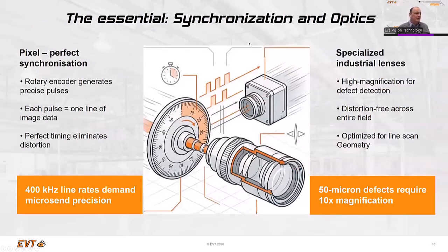Of course, the essential part, which I just mentioned at the very beginning, for the line scan camera application is that you need accurate timing for the line capturing. So one option would be, which is not a really good option, that you have a belt which works very continuously and you know exactly the speed. Then you could run the line scan camera freely with the hope that you never have any stop or something else. Or the really good solution for line scan cameras is always encoders.